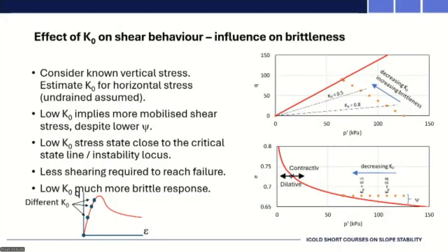If you have already imposed a large amount of shear in the ground, as shown by the dot that I'm pointing at there, you need a very small trigger to take you over the top and induce liquefaction. So we should not only worry about the state parameter, but the in-situ stress state is also crucially important, and that is something that is hardly ever measured.